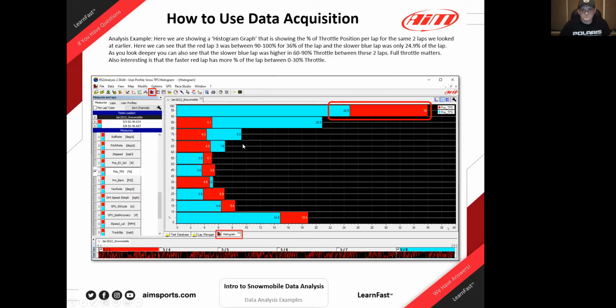And it takes it, and these are in 10% buckets. So this top one here is 90% to 100%. We call them bins. And it's breaking this down and saying, you can see the red lap is showing but behind the blue one. So it's got the most percentage of a lap compared to the blue one. It's at 36% of the lap was at between 90 and 100% throttle for the red lap, the one that was slightly faster, 1.6 seconds faster. And the blue one was 24.9, 25%, right? So 11.1% more of the lap on this faster lap was the rider at between 90 and 100%.